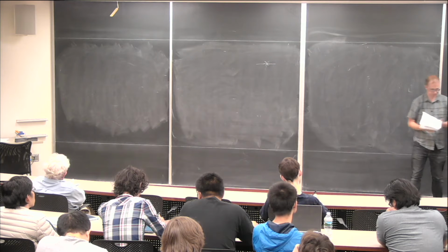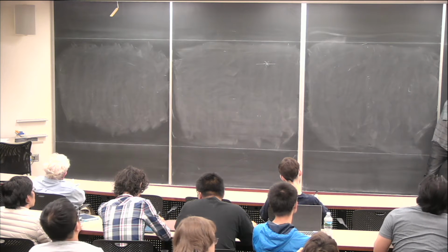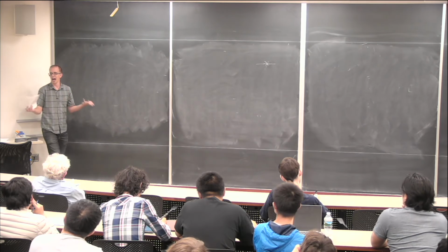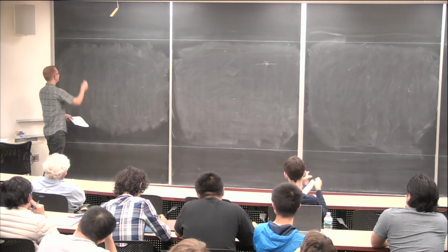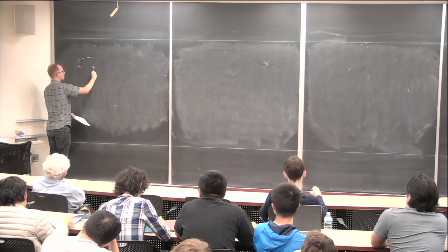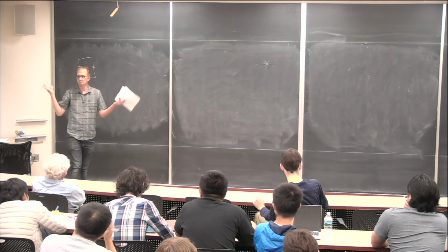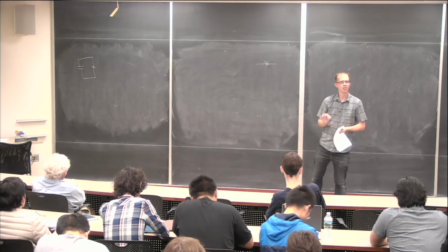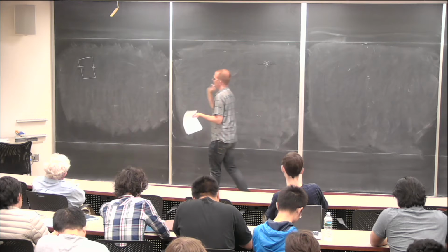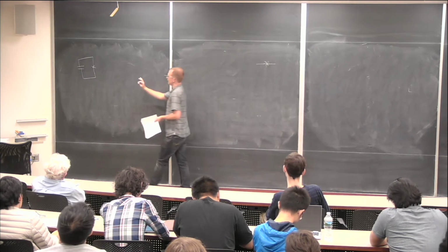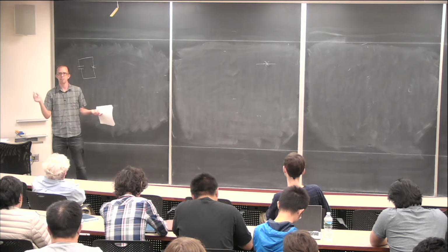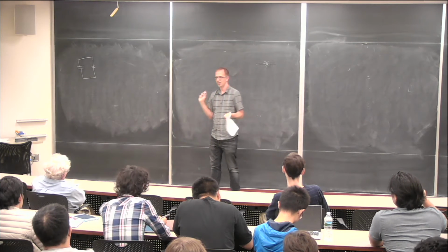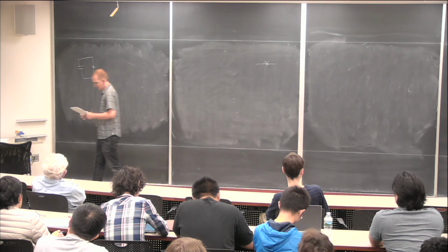Okay, so the simplest thing you could think of if you were trying to design a circuit, given that I told you we now have a nonlinear inductor, is you could take a capacitor, and instead of putting it in parallel with an inductor, you could put it in parallel with the Josephson junction. It turns out that this qubit, depending on the range of parameters, how big your Josephson junction is to how big your capacitance is, behaves very differently, and we're going to go through that. But in some form, this is the qubit that most people in the field use today, even though it was one of the later qubits to actually be discovered and used, in exactly this way. So it's a little bit counterintuitive.